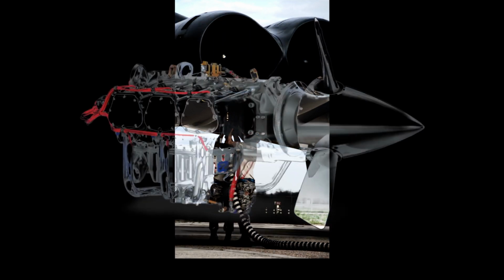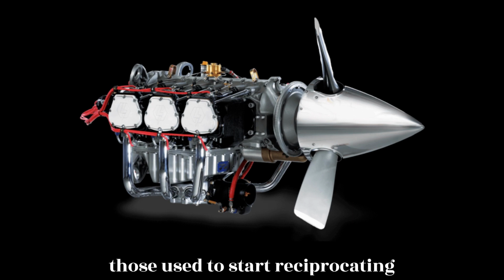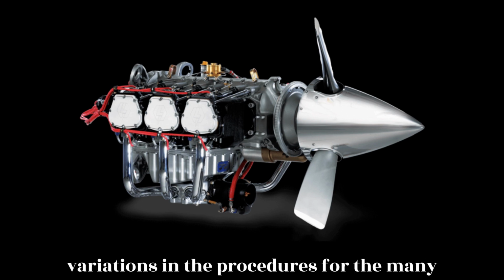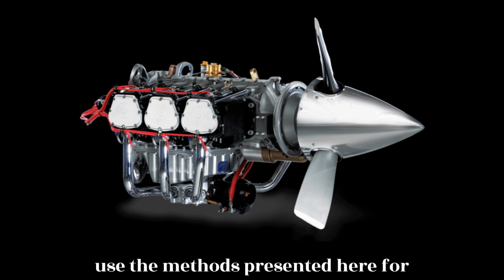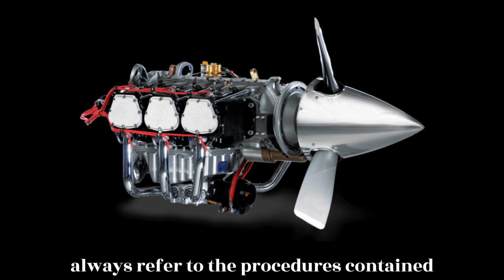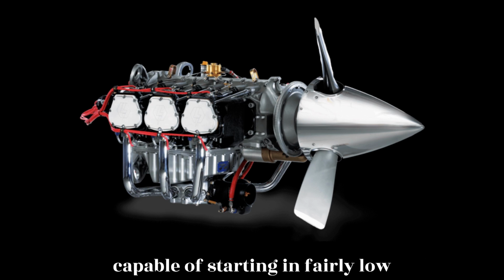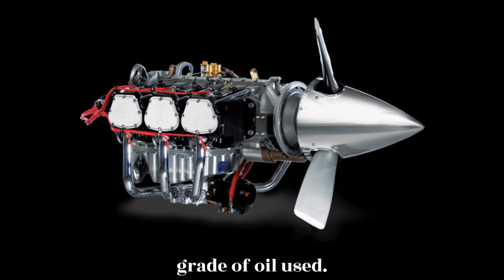Reciprocating engines. The following procedures are typical of those used to start reciprocating engines. There are, however, wide variations in the procedures for the many reciprocating engines. Do not attempt to use the methods presented here for actually starting an engine. Instead, always refer to the procedures contained in the applicable manufacturer's instructions. Reciprocating engines are capable of starting in fairly low temperatures without the use of engine heating or oil dilution, depending on the grade of oil used.